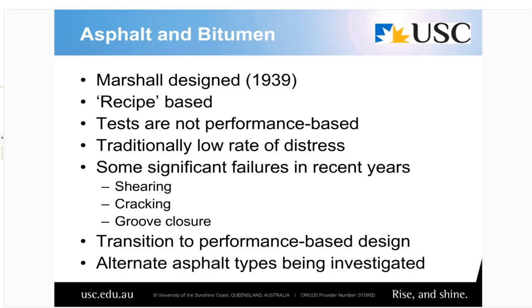And the other thing that is probably contributing is the variability of bitumen supply, introduced as a result of the importation of the majority of our bitumen. Not that imported bitumen is necessarily worse, just that if we know how to treat bitumen source A and then tomorrow we suddenly get source B and we're still treating it like we are A, we'll end up in our car with our indicators on when we tried to turn the lights on, or vice versa.